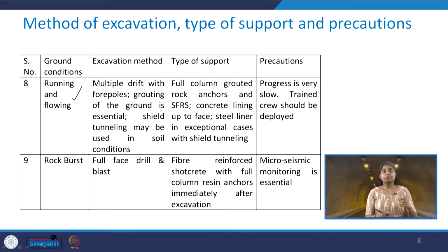But here I have clubbed these two under one category because of the similar treatment which is to be given if the excavation is made through such ground conditions. So, the recommended excavation method is multiple drift with poles. Grouting of the ground is essential in this case, and shield tunneling may be used in the soil conditions.